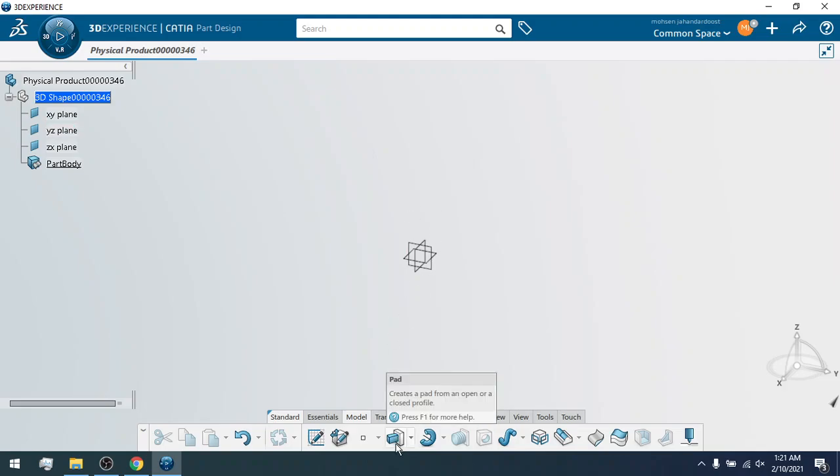The extrude cut and extrude boss are the fundamentals of creating an object. This is the easiest and most used command to create the base, and after that you can start cutting and removing the material to get to the final shape that you have.